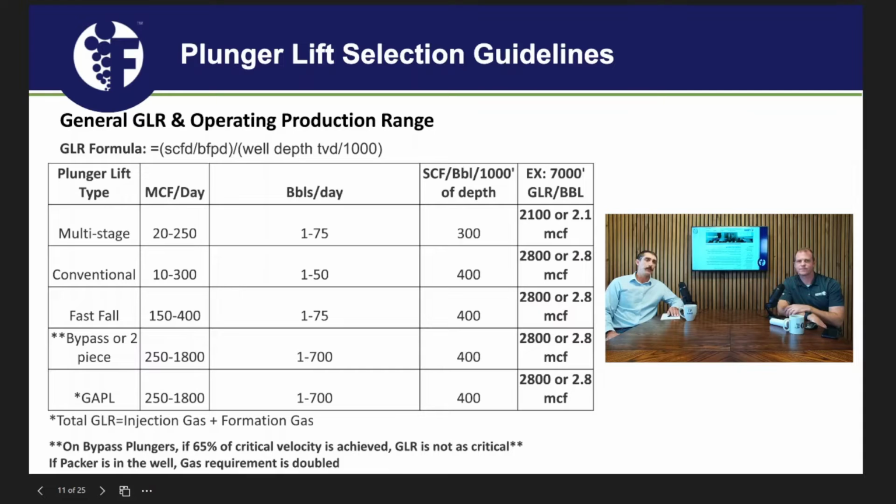Okay. And there's a lot of other factors. If you do that with 500 pounds of wellhead pressure, it's obviously not going to run. Correct. But really, just in a nutshell, that's a quick way to look at the GLR. Something I often say that's not on here is a 5,000 GLR, in standard cubic feet, is the minimum you want. Okay. Anything over that, gas is our energy, right? So that's the minimum. Anything over that will definitely run a plunger. Gotcha. So that's just if it will.